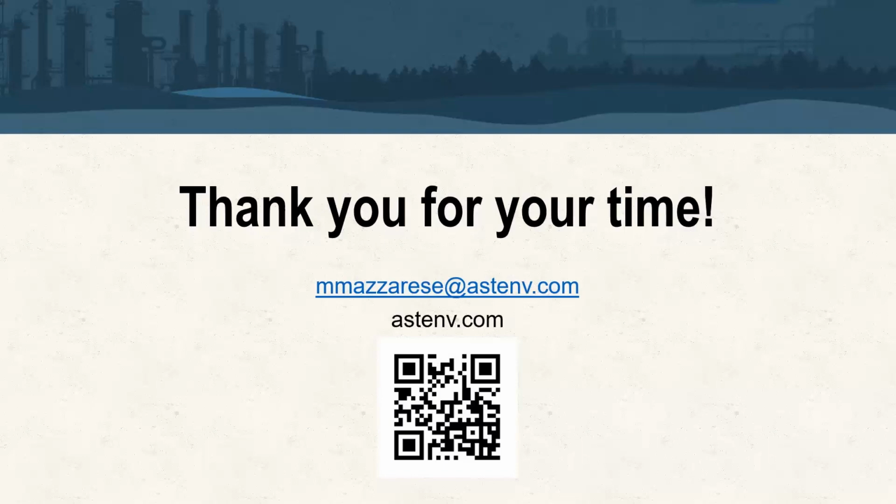So your day is going to look a lot different because you're going to get rebound, which we did see on that last site, even with this. But I think in general, you have to have that kind of extreme situation and quite a lot of saturated soil mass to be able to drive that, because that's a strength of the activated carbon, it helps wash out that rebound that you see with typically ISCO. So from a time frame standpoint, it's hard to say.